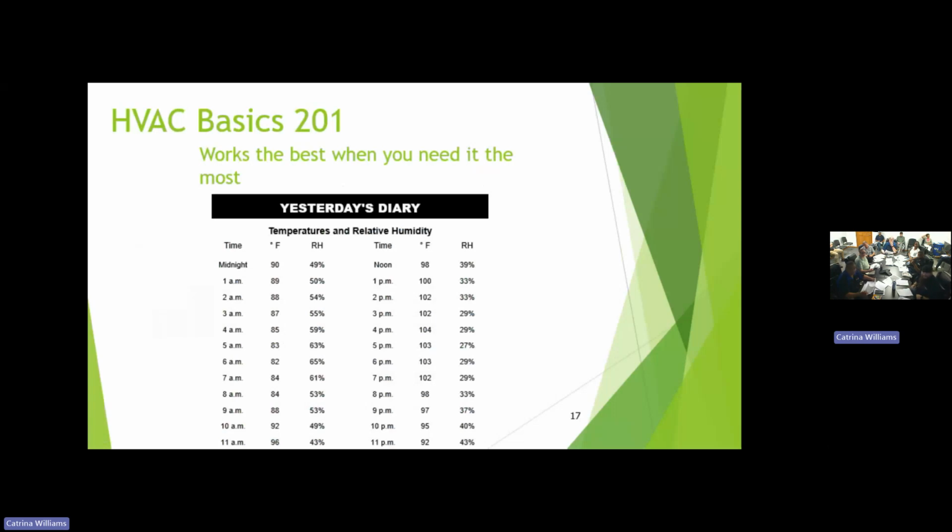So again, if you hear the weatherman say that it's 104 and 29% humidity, if you look at this, you get a pretty good idea what the wet bulb temperature is, because they don't talk wet bulb in the weather stuff like we do. Okay. But you have that number and you have a psych chart, you can determine it.